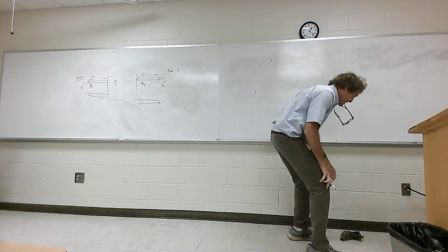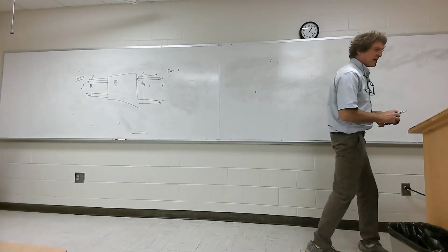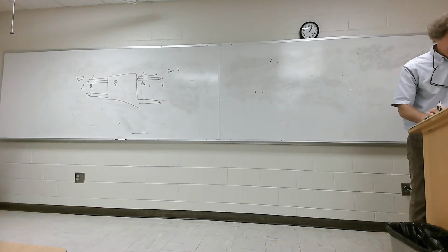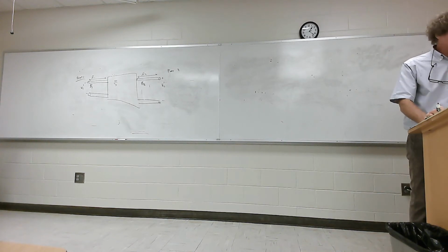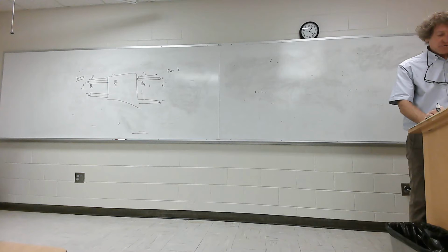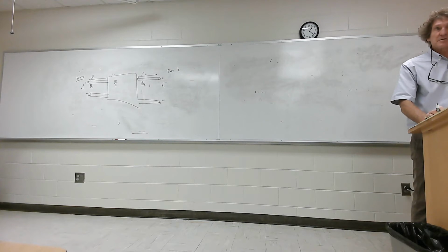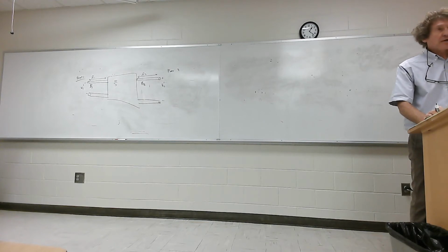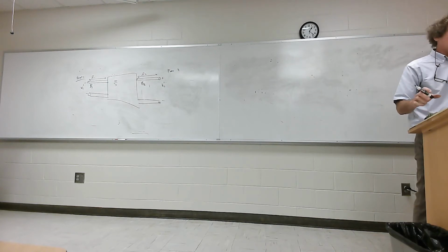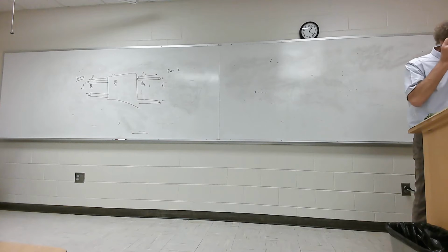And when you're doing this, he shows a real S parameter measurement on page 567. You have your books there. If you look there, you'll see he's got a device and he has 2 cables connected to it. And the computer will catalog all the values of the S parameters as he sweeps frequency. It will not be at just one frequency. He'll sweep over a range and he'll have the S parameters. So then,